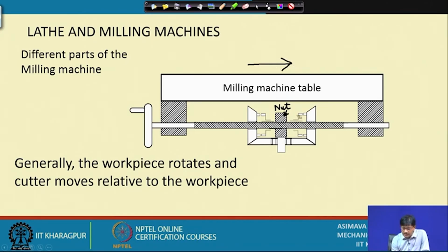What are these things on the sides? These are bevel gears. So, there is a basic cradle bevel gear or a crown bevel gear here, and connected to that there are two bevel gears which, if they rotate, they are going to move all around. Okay. They are going to move on these circular rails. It's just like a merry-go-round. They will go around in a sort of merry-go-round motion. Okay. So, if I rotate this handle, this screw moves through and the table moves.